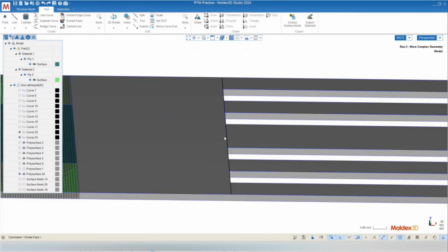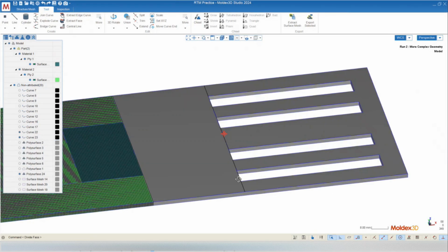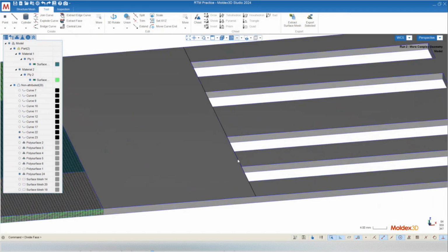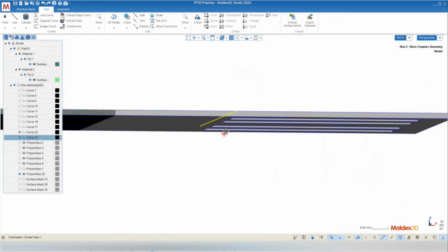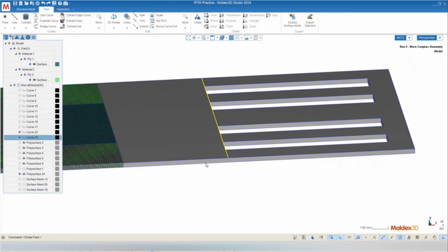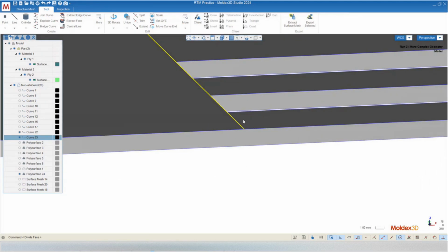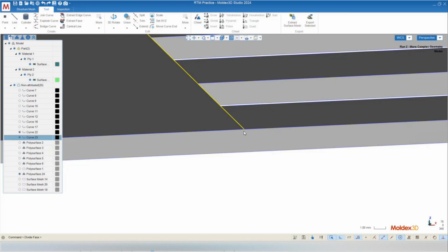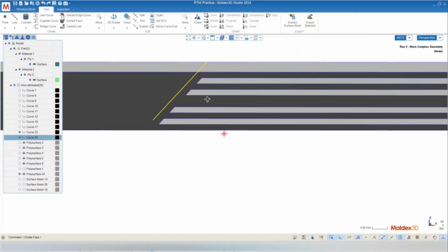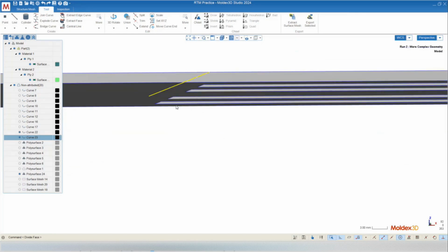Now, just to maybe eliminate that occurrence that we had over here, where we had to copy the mesh, because we have that foresight, let's go ahead and do that divide face one more time for the bottom surface. Now, I could do the same thing. I could create the 2 lines on the bottom surface the same way I did on the top. But since I have this line, what I could do is actually copy this line from here down to the bottom surface perpendicular. Since this is an extruded geometry, you won't always be able to do that. So it might be more consistent to create the lines again.